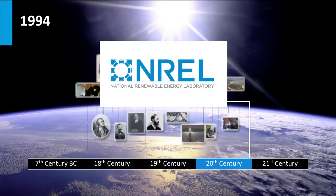In 1994, NREL in the US developed the concentrator solar cells based on III-V semiconductor material. The cell, based on a gallium indium phosphide, gallium arsenide based 2-terminal concentrator solar cell, exceeded the 30% conversion limit. The concentrator PV technology will be discussed in weeks 5 and 6.